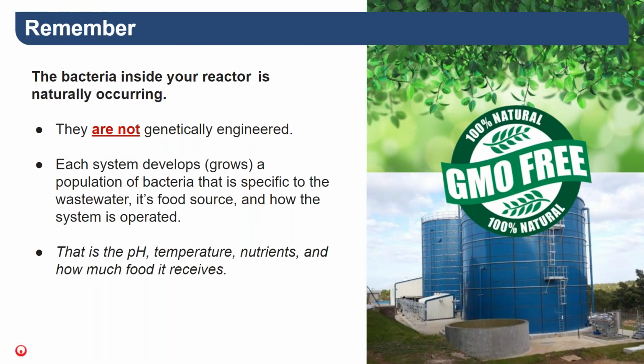Another thing to remember is that the bacteria inside your reactor that are doing your work, that are doing this COD reduction and cleaning your wastewater, they're naturally occurring. They're not genetically engineered. Each reactor at each plant, even if you go from brewery to brewery, brewery A and brewery B are going to have slightly different bacteria populations in them. Each system develops a population of bacteria that is specific to that wastewater, its food sources, and how the system is operated.